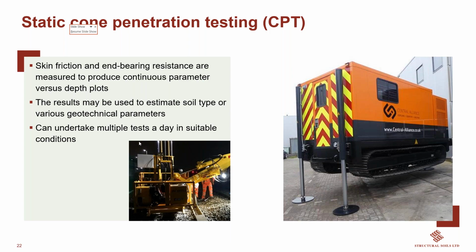However, this doesn't retrieve any samples. Again, it's a very useful tool, and we can cover up to 100 meters a day. However, we do need to supplement it with, let's say, cable percussive drilling, so we can correlate the samples that we're getting with the results from the CPT tests.